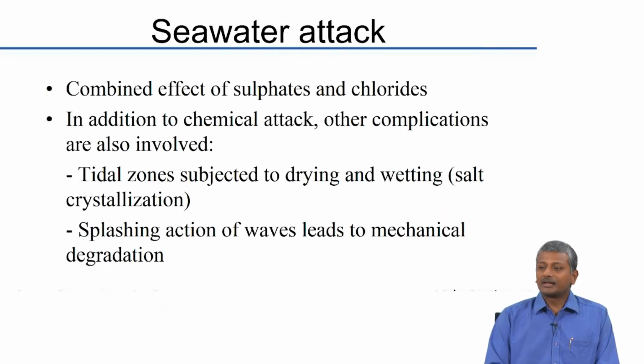So, continuing from our discussion yesterday, we will look at some other instances of chemical attack of concrete. We talked about sulfate attack, delayed ettringite formation, chloride attack, and we also talked a bit about acid attack, which is emerging as an interesting field of study because there are a lot more instances of acid related damage that people are finding in concrete structures. Seawater attack is a combined attack of sulfates and chlorides, right?